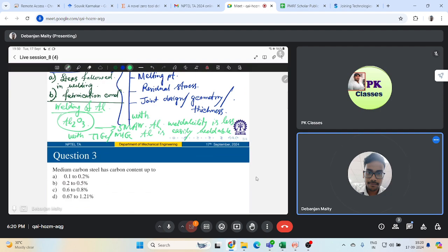Got my point? Similarly, let's say you are joining steel metal. A steel weld joint may perform well under some normal atmospheric condition, but the same metal may exhibit very poor toughness or poor ductility at some sub-zero temperature condition. So depending on your welding condition, your processing condition, for the same metal, my weldability can vary, right?